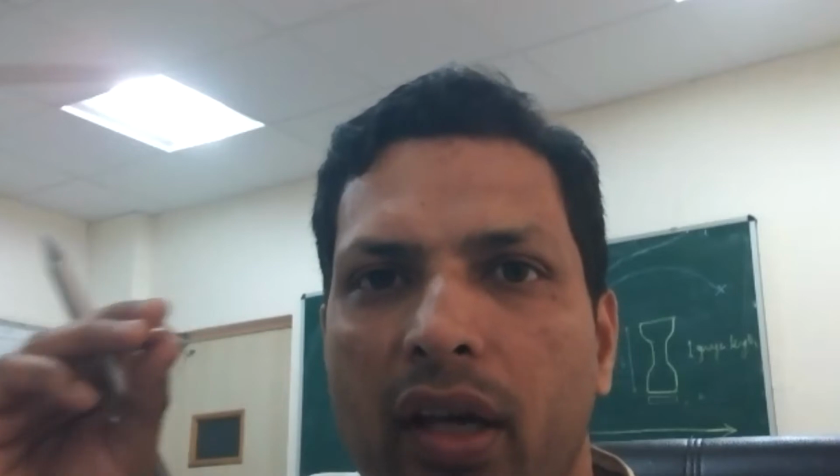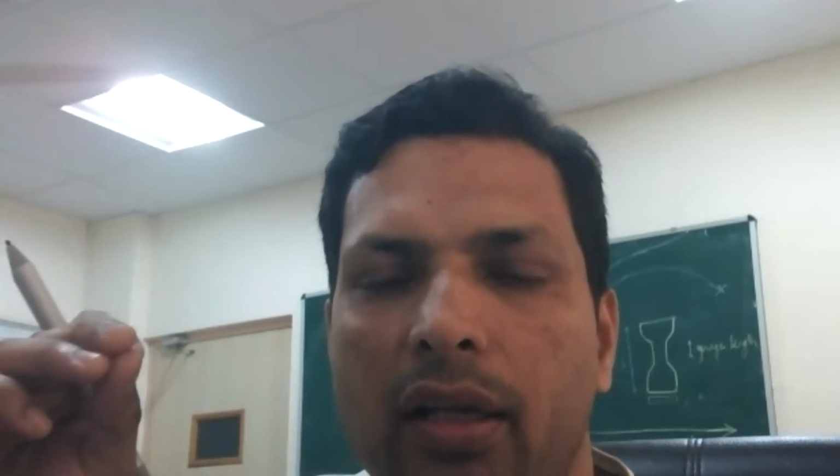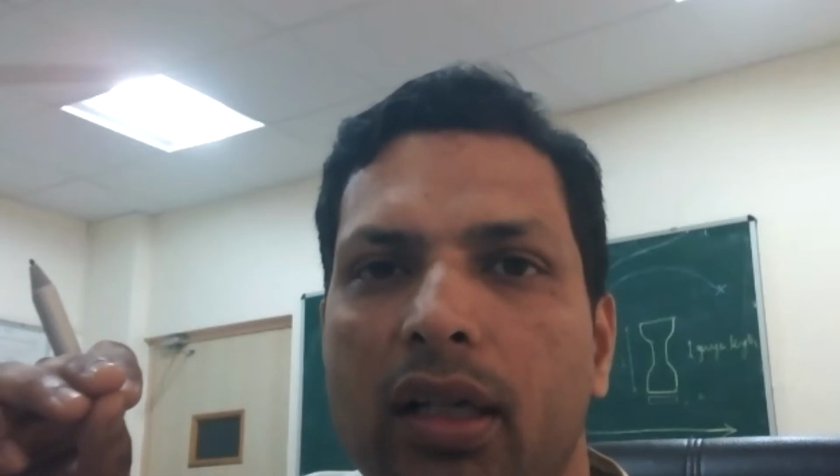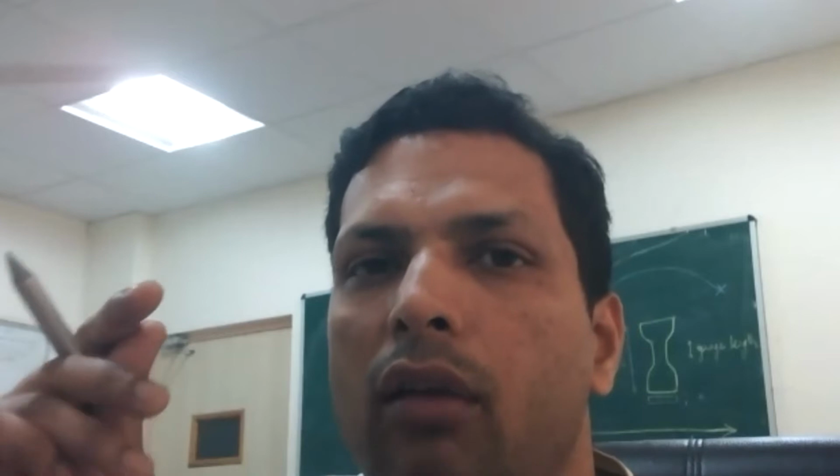What this implies is that very near the surface, some thickness, which we will be able to calculate, you will have no dislocation. The other implication is that if the dimension of the material is very small, let's say we take a whisker, a rod, which is 2 times this thickness, then it is almost completely free of dislocations.